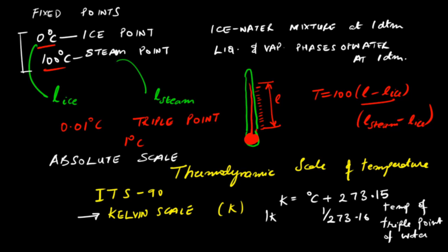And the zeroth law allows us to measure temperature in terms of the variation in thermometric properties of different materials. For example, the length of the mercury column in a mercury-in-bulb thermometer, or the pressure of a gas in a fixed volume bulb, or it can be the resistance of a material which changes with temperature, or it may be the potential difference between the two ends of the wire which are connected by a junction which is maintained at different temperatures. So that is used in a thermocouple.